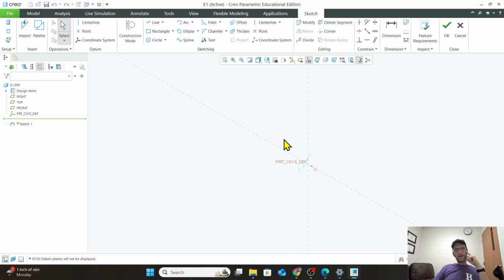All right. So we have our left mouse button, a left click, a right click, and we have our scroll wheel in the middle, which can be clicked and scrolled in and out. If we scroll in and out on that scroll wheel, we're able to zoom in and out. The nice thing about Creo when we're working with a model is that wherever we leave this mouse pointer, this cursor, wherever it is lying on a part is going to help us center where we're going to head and zoom in on things.